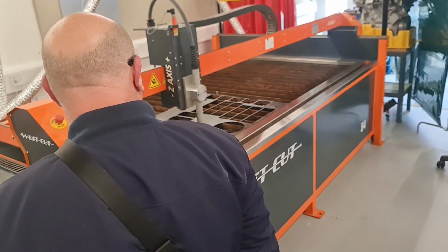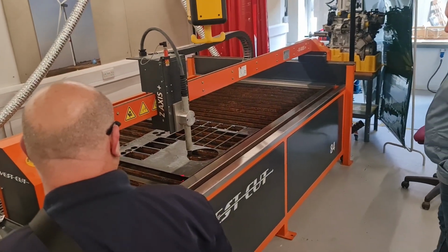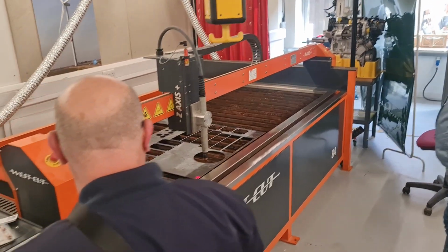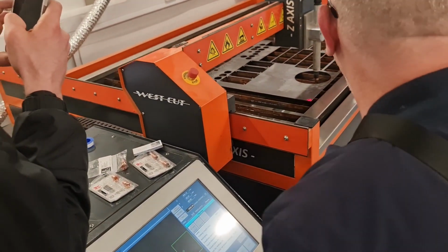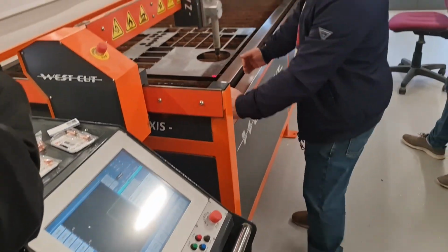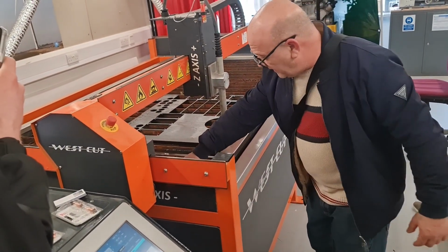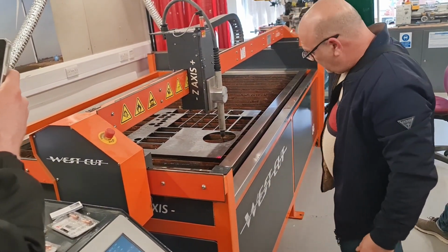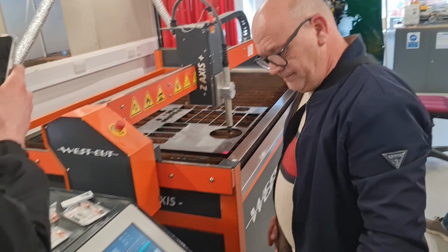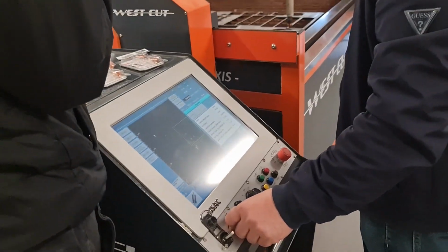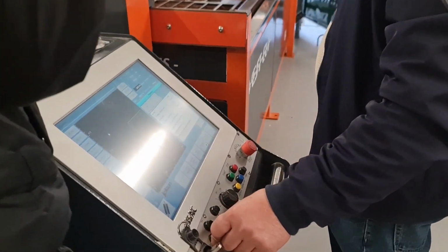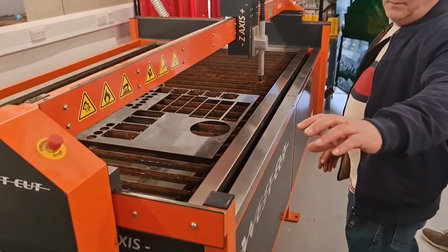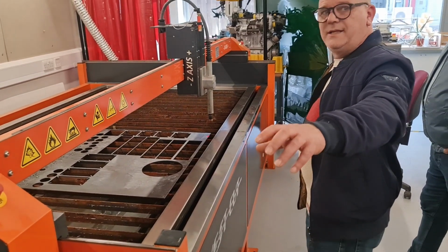So what I'm going to do is, first, a good idea will be, if this one will be square with the machine, then you have a piece of flat bar here, you just hit it there and start. But let's do it the hard way, this way. So I'm going to align the machine in the place. It's not necessary because the machine can also rotate the part.